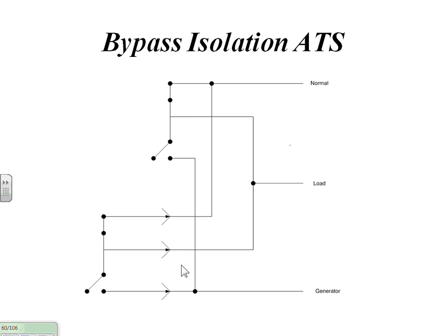Now, this thing fails, we have to rack it out. All you have left, this lower part here is now gone, and we're on generator power. The guy's on the table, the doc's got the knife. So normal is gone, it's dark because the automatic switch is dead. We have to go up and manually close this guy. So now the generator can provide power up through here, through the switch, and out to the table.